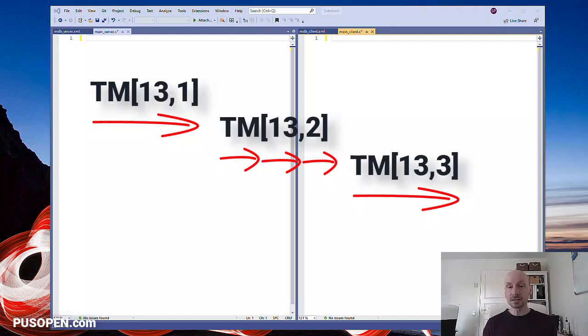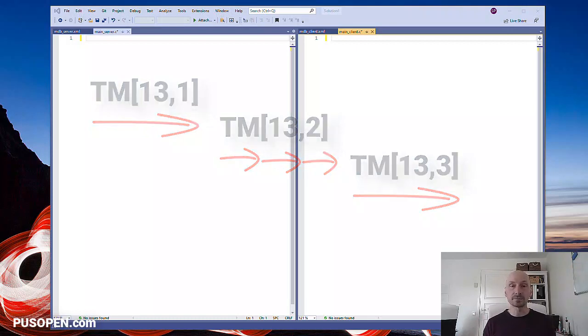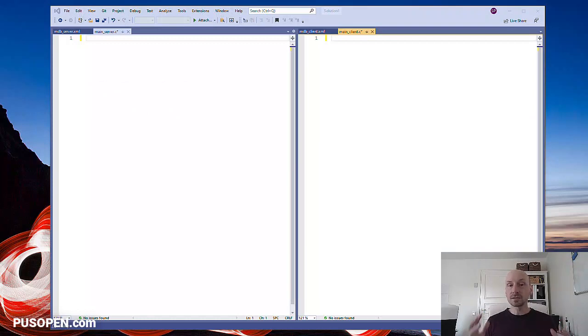A similar sequence then exists for large data uplink, when you want to uplink, let's say, a command set to your satellite to tell the computer what to do until the next communication session. In this demo, the server uses PUS Service 13 to send test data from the buffer that we define to the client. The client will then simply print out the received data.